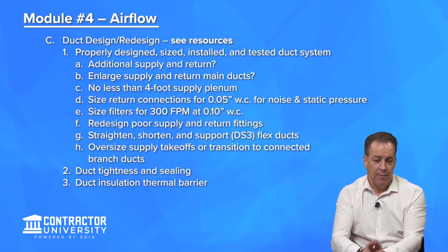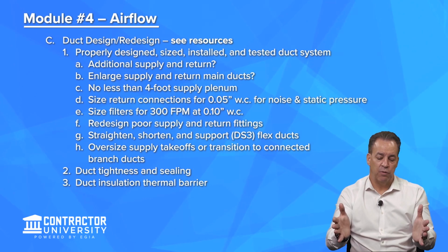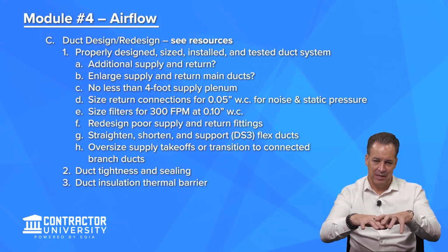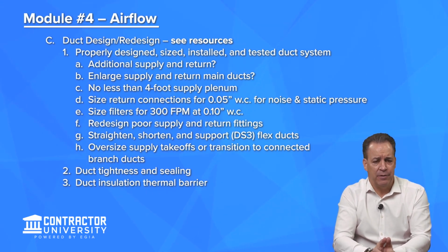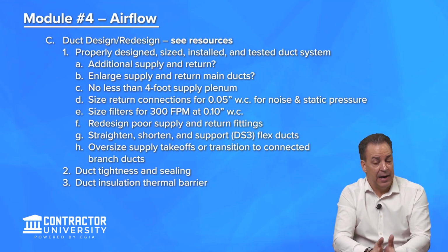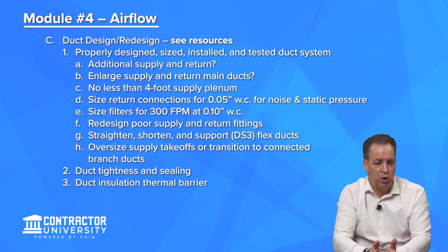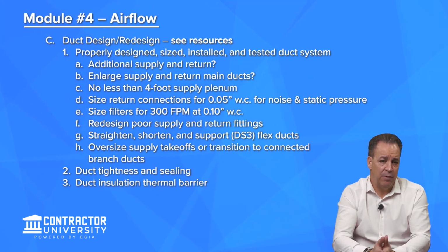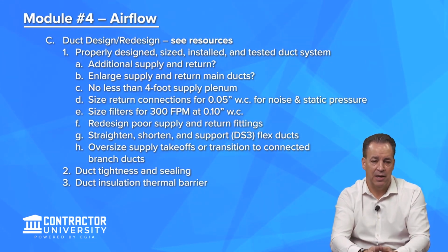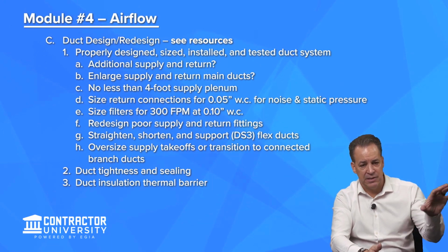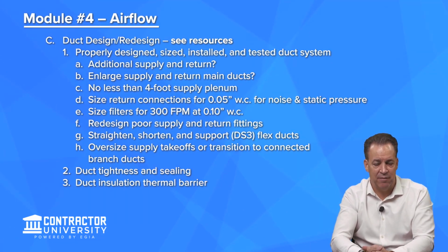Now, there's some school of thought about duct board. It's an insulated fiberglass board that's rigid. There's some thoughts on that, and again, it can function as ductwork, but would you want to be breathing insulation? And as that ductwork breaks down over time, you're going to find out that a lot of the atmospheric dust in the house is made up of the insulation in and of itself. A lot of the floaters in the sunbeam you'll see is made up of the insulation in and of itself.